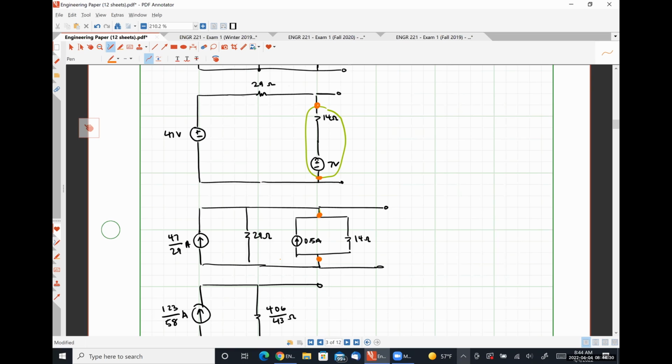So I explicitly set up terminal pairs, disconnect the practical source that I'm transforming, connect back to that same set of terminal pairs the electrically equivalent practical source, and then go to my simplifications. If you don't get into that mindset where you're looking specifically at your terminal pairs, taking something out and putting something back in, it's very easy to make a simple mistake.